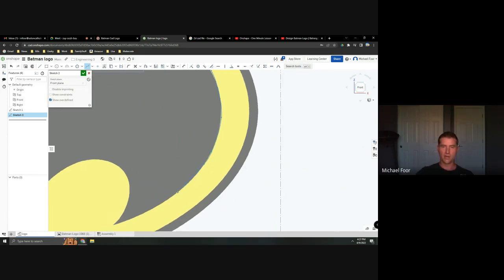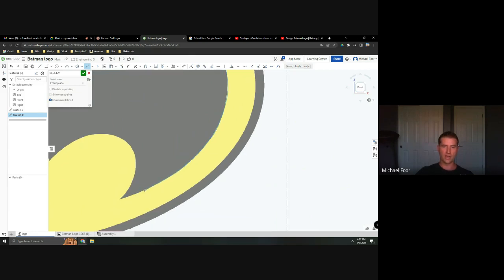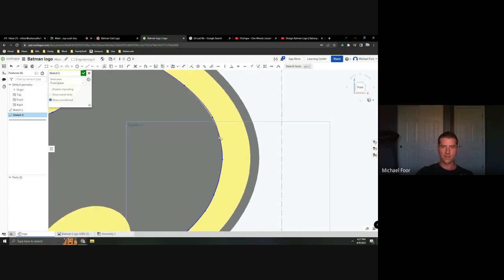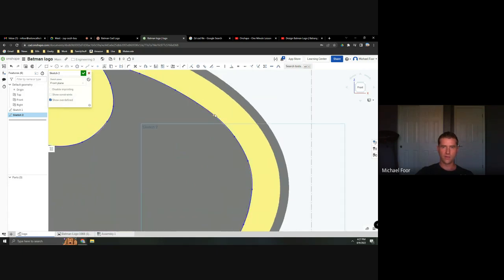Now you have to hold down when you click and then drag it around, and that's going to force that point. But again, don't worry about getting it perfect the first time. You can always go back and finish it up. So right here, I'm going to double click there. There's my spline. I can see there's some real rough edges. So I'm going to hit escape, and there I have no tool selected. And now I can just go back. And that's the nice thing about the spline. It keeps the curves regular and nice and smooth. So I'm going to go back and just tweak these until we get this really nice shape.